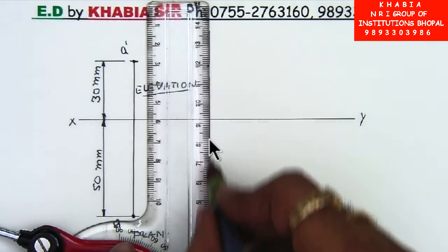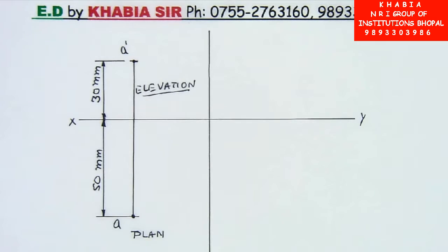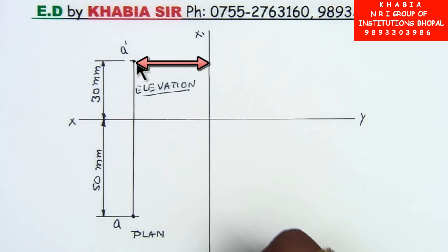First, we draw the side reference line perpendicular to the horizontal reference line. The question arises, by what distance will the side reference line x1, y1 be towards the right side of the front view. And the reasoning comes out from the 3D model.